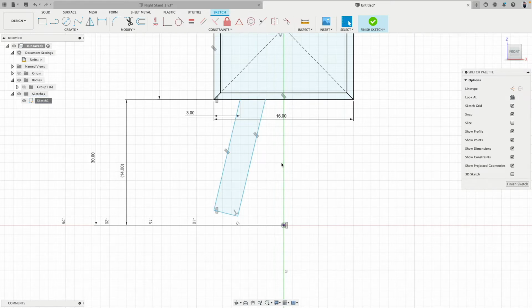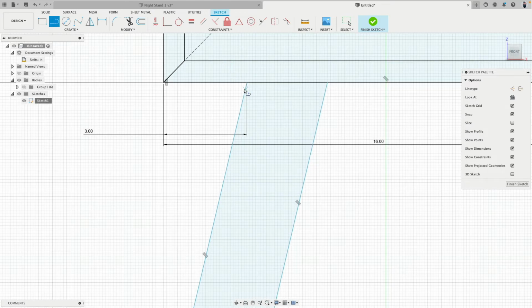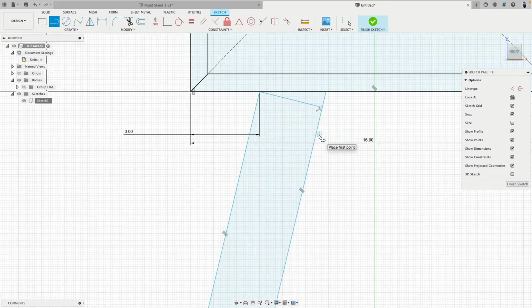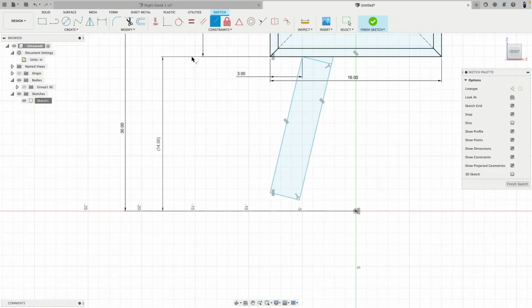So, yeah, how do we continue? I will do the following. I will draw here somewhere. Actually, I will draw a line here at this point. Go down, and now I need here to figure out where does it show that it's perpendicular. There it is. And if you don't see it, we can also simply go perpendicular and say U to U, perpendicular. Now I have a midpoint and another midpoint. This line I can select, press X for construction. This was just kind of like a helper.